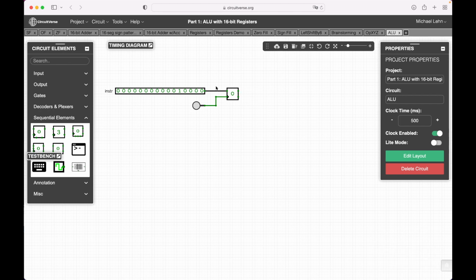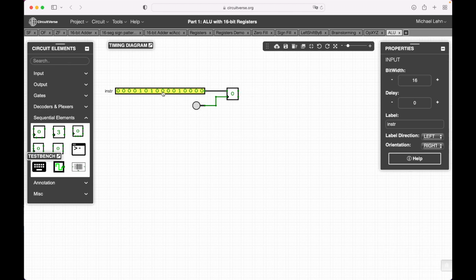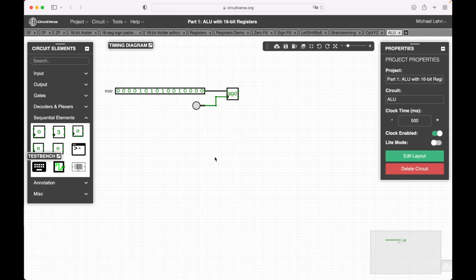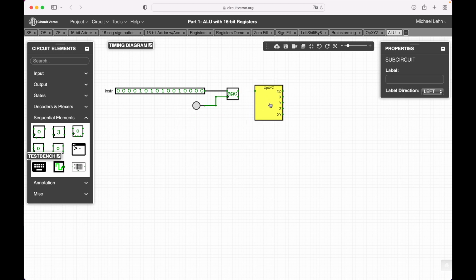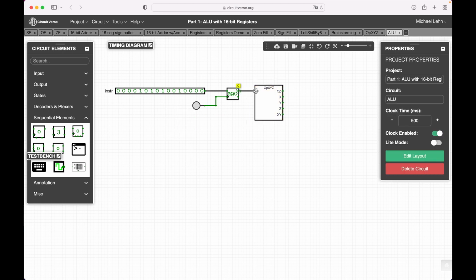And so you first type in here some instruction, and then it gets copied into the instruction register. Usually this instruction would be somewhere in memory, and then you would copy it into the CPU. Then it gets decoded, which is in this case simple because everything goes, in our case, to the ALU. So this decoding is just these splitters hidden in here.